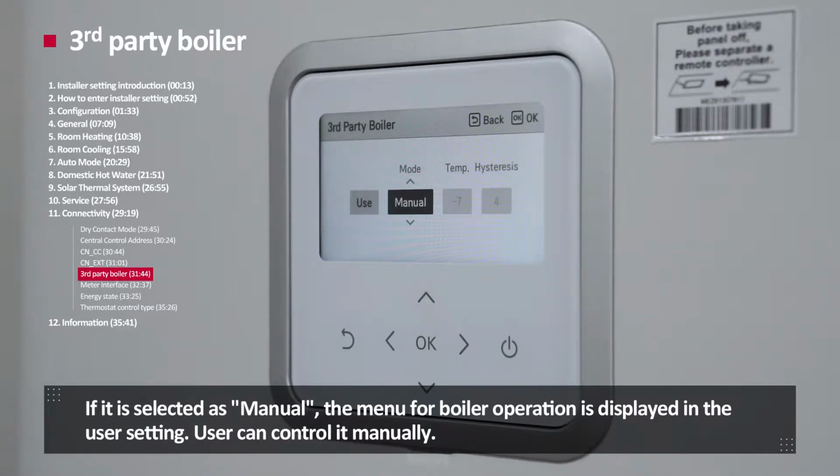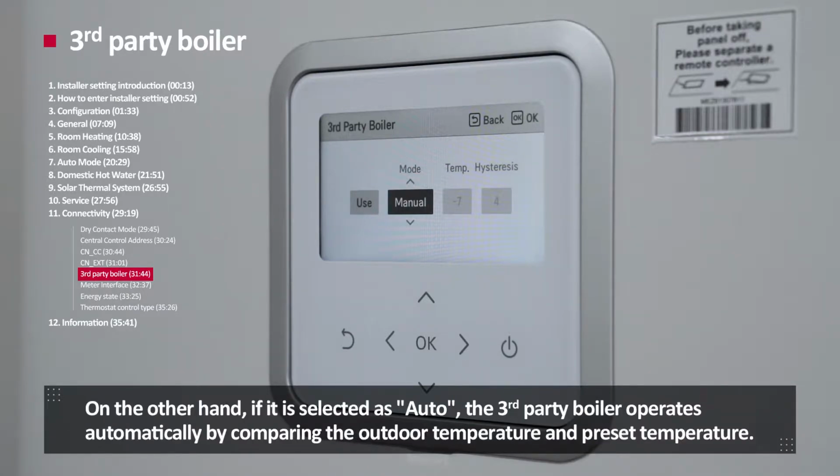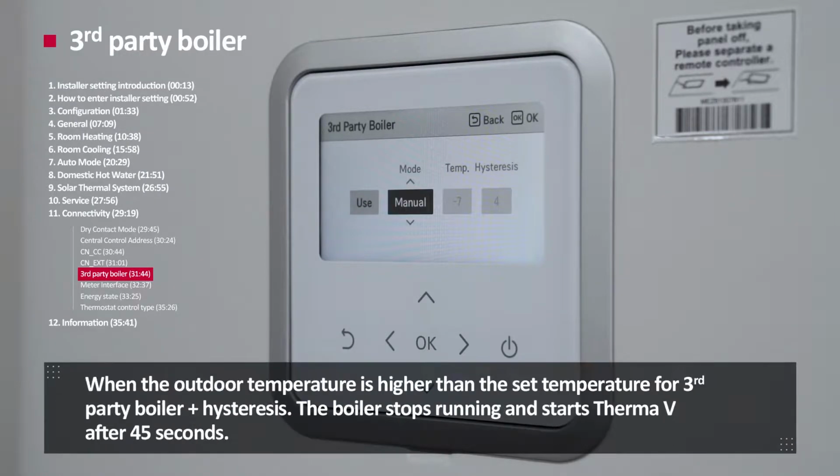User can control it manually. On the other hand, if it is selected as auto, the third-party boiler operates automatically by comparing the outdoor temperature and preset temperature. When the outdoor temperature is higher than the set temperature for third-party boiler plus heat statuses, the boiler stops running and starts Therma V after 45 seconds.